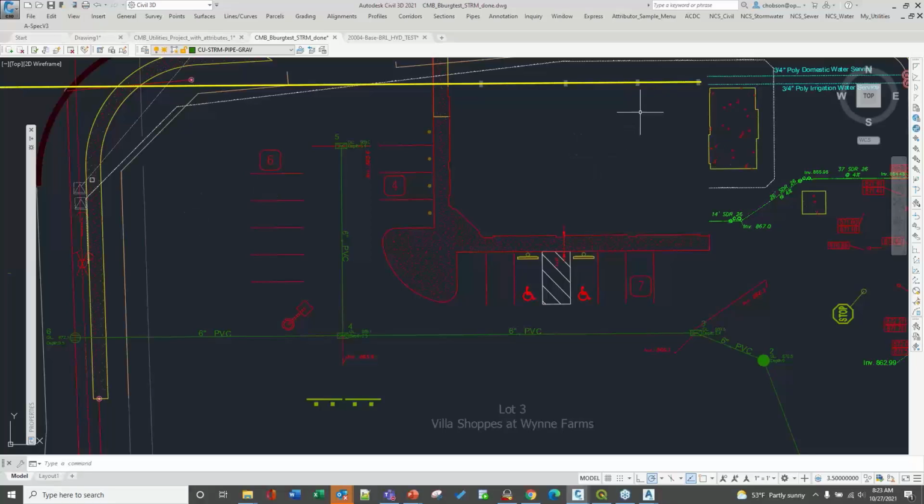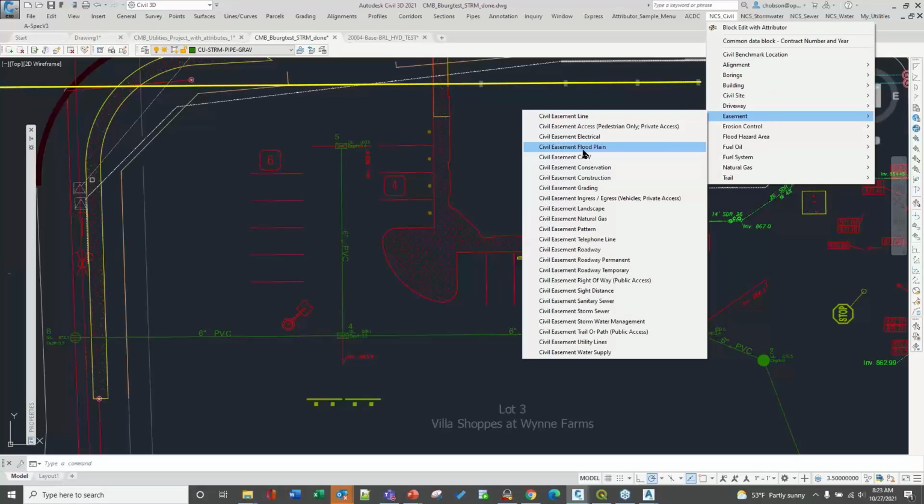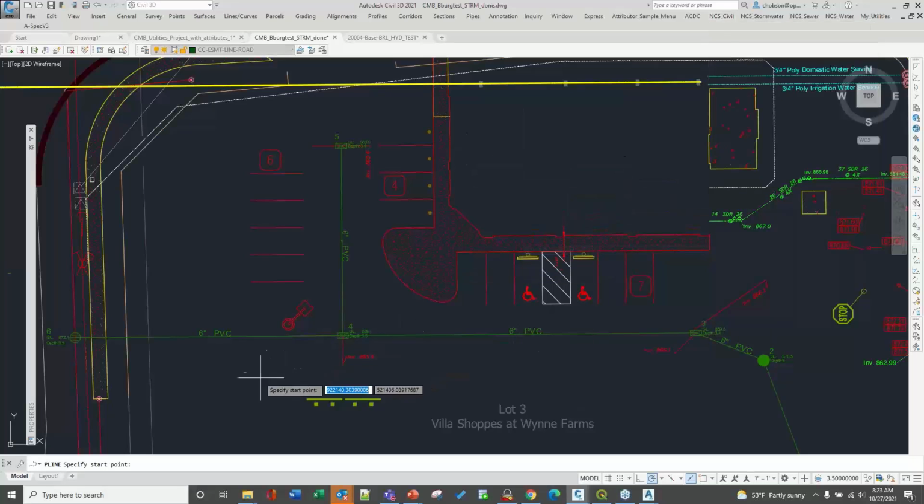So what you do is you put it on a menu. What we've done, for example, is a National CAD Standard-based menu, so that if I want to draw something like an easement, it's already there, and these are the layers, and that layer information is going to be useful for moving it over to wherever.